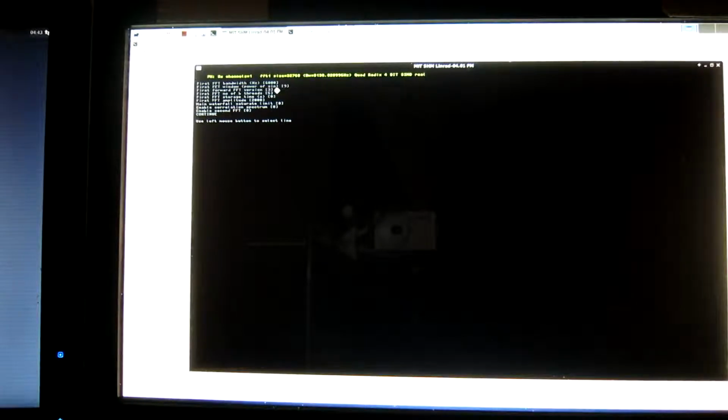That is the FFT, first forward FFT version number 3. It computes 4 FFTs in the algorithm in parallel. There are 5 threads doing that in parallel, which means that there are in total 20 parallel computations of the bulk of the FFT. The window is number 9. That's an expensive window, but it gives the best alias suppression.